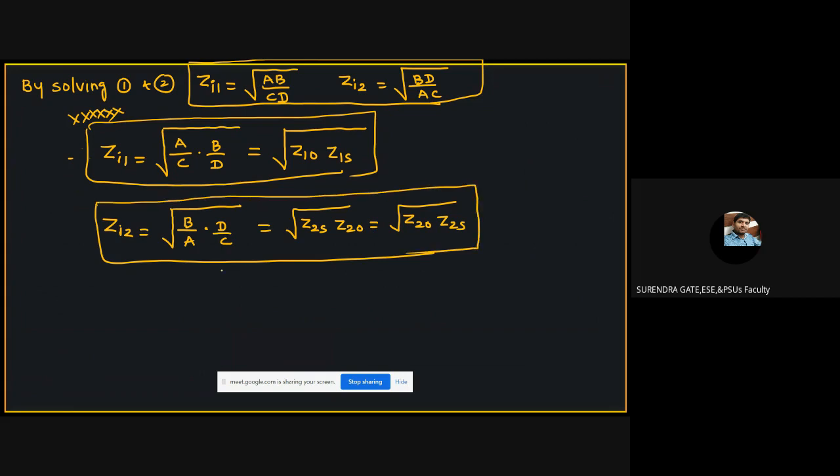But point to remember, friends, to define the two-port network completely, only image impedances are not enough. That means the image impedance itself will not completely define the two-port network. Because of that, we need to define another parameter. That parameter we can get from the voltage and current ratios.